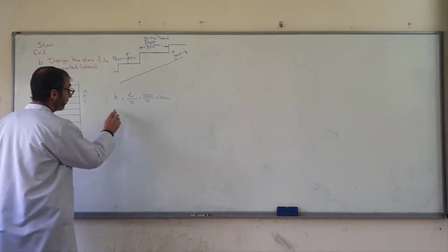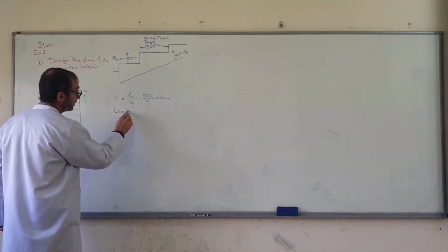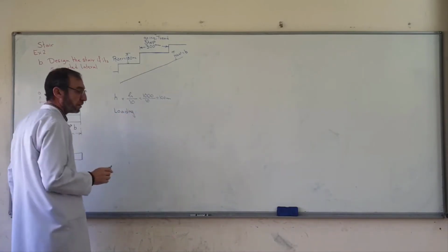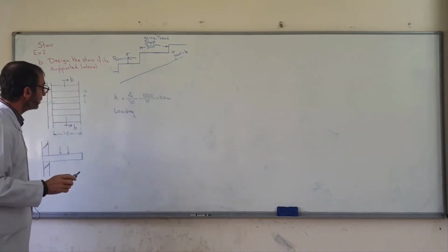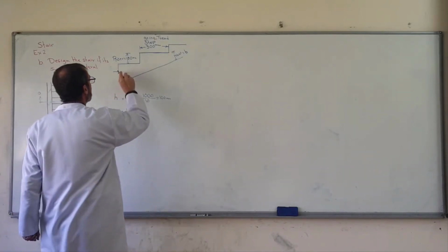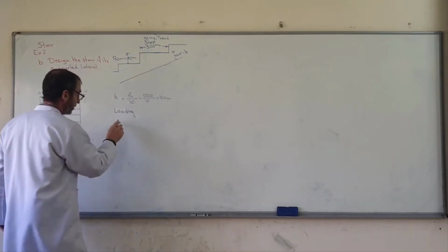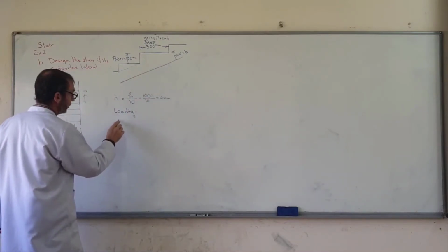Now I go to find the loading on the slabs. Loading includes the self weight of the steps, as we know: self weight of steps plus waist.